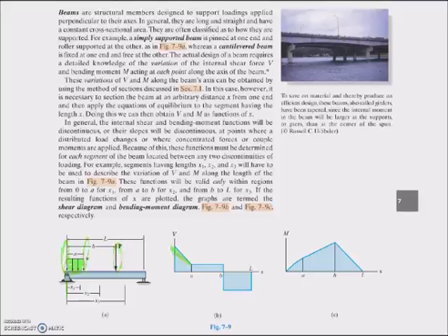Where there is an applied force, there's going to be another rapid change in the shear, and then where there is a reaction, there'll be another discontinuity or another sudden change in the shear. So we'll again understand that as we go along.